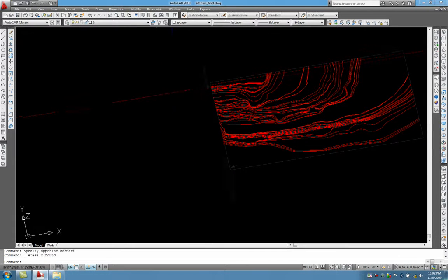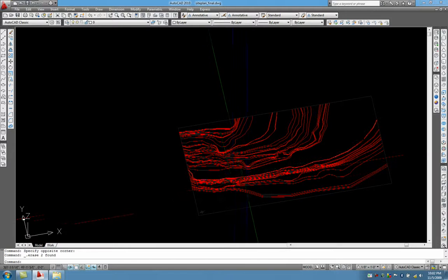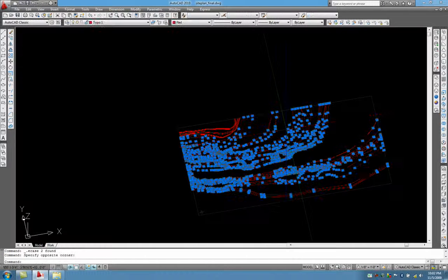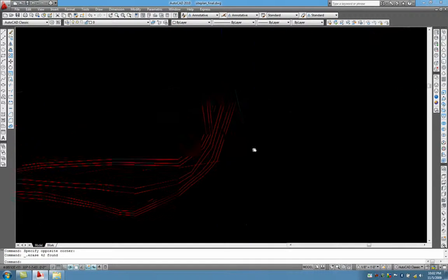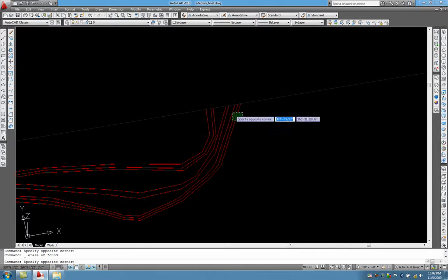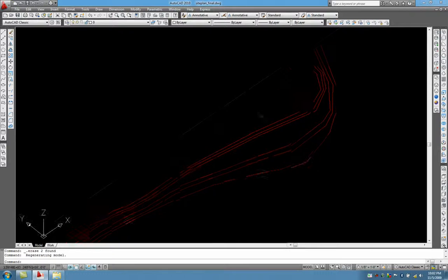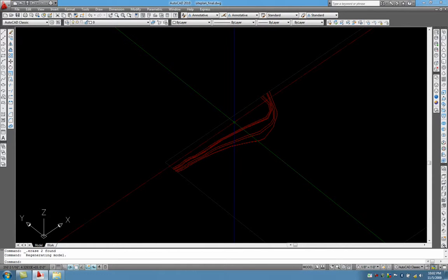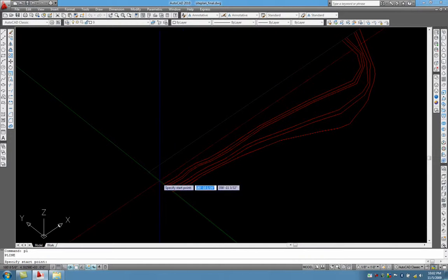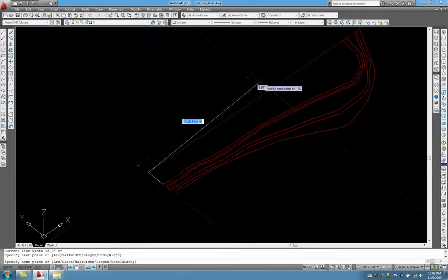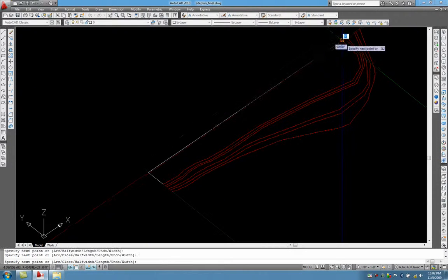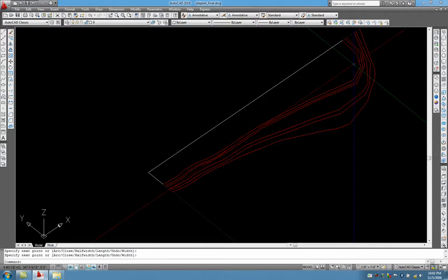So delete these real fast. I'm going to delete a bunch of these other lines because I'm not going to go through and loft all of them. I don't want to do all the work. So anyway, here we are. We've got just a few polylines, and we need to close them. So I'm going to type PL to draw a polyline here. I'll draw it to that corner and then to the end of that. Enter. And now that polyline is done.